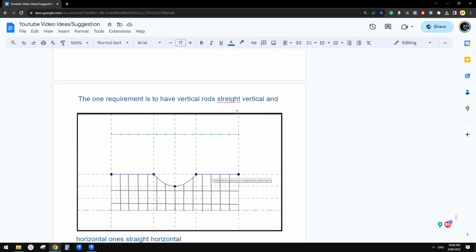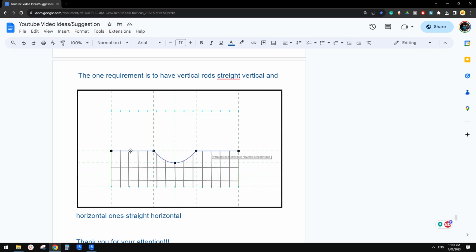it's like a railing, but it's an adaptive family, so vertical straight. So need to be straight. All these need to be vertical straight and horizontal straight as well. But then there's a curve in the middle here. I think the issue we have here is that if it's a straight line, it can be quite easily divided by using divided path, something like this. But once there's an arc and it becomes 1, 2, 3 parts, we can't do that anymore.